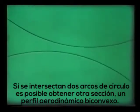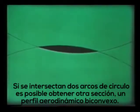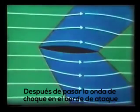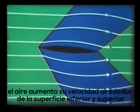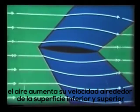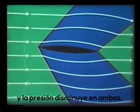Two arcs of circles go to make another possible section, the biconvex aerofoil. The thickness here is again exaggerated. After passing through the shock wave at the leading edge, the air speeds up gradually round upper and lower surfaces, and the pressure is reduced on both.